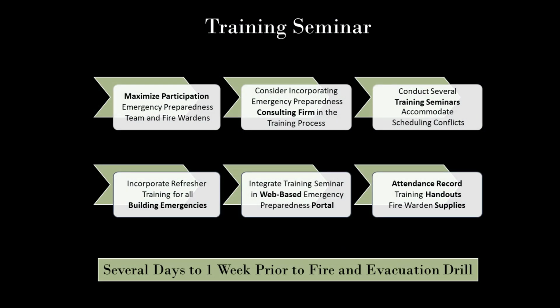Formal training of the building's emergency response and tenant fire warden teams is essential and is best conducted within 1 week of the fire and evacuation drill date. All members of the building emergency response team, including facility management, operations, security, and tenant fire wardens, participate in the training session with attendance documented and retained as a permanent building record.